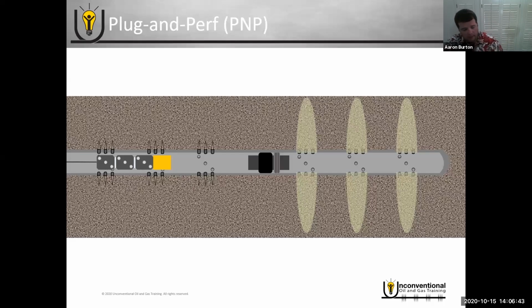Now, 3 to 5 clusters per stage used to be common in most of these plays about 5 years ago. But within the last couple of years, it's actually pretty common to see more like 6 to 12 clusters per stage. And the reason you can do that is because the technology with the perforating guns has drastically improved. So the switches in them and everything else, you can individually fire perforation guns and essentially have an unlimited number of perforating guns. So the practical limitation with the guns is not going to be the perforations or the perforating guns themselves. It's going to be the length of the overall assembly.